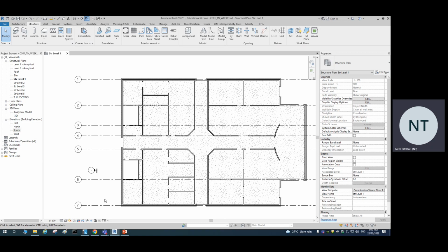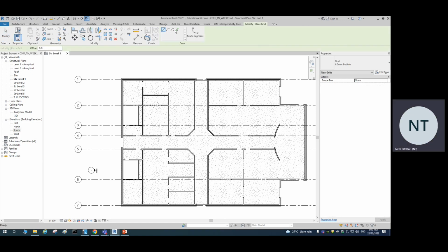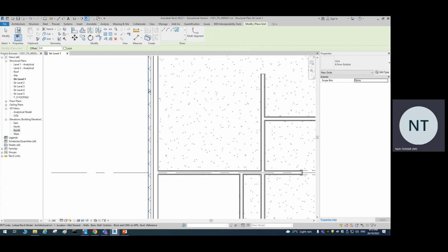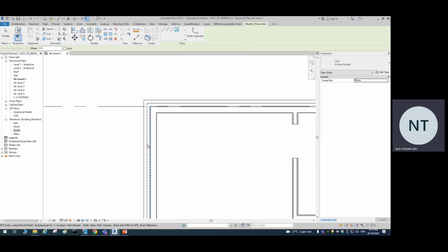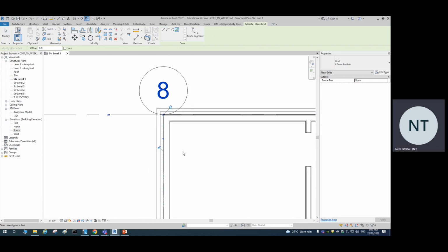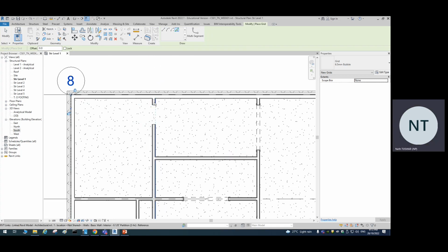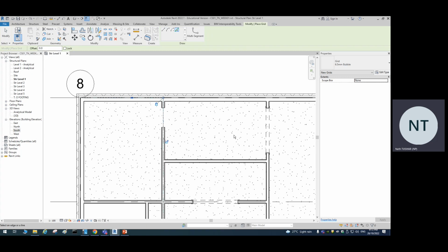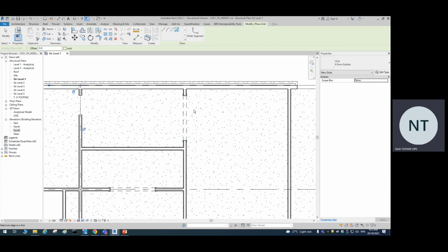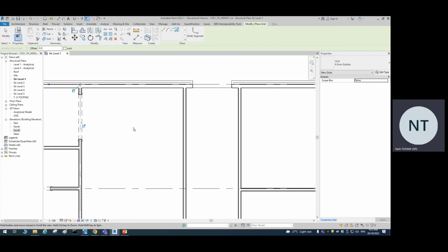Okay, grid line on this one horizontal. Now let's do grid line on the vertical side. Same thing. Structural tab, grid line. Again, pick lines. I'm going to select the center line of this wall, this vertical direction, let's say. Okay, center line of this wall, then center line of this wall as well. Those who have got it, you can proceed already. Proceed to do the grid lines.